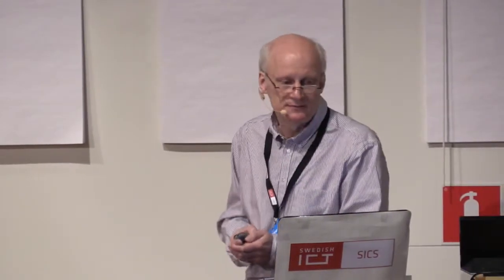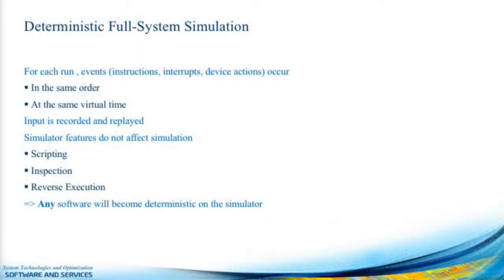So, what do we do about this? Well, what I'm proposing is to use a deterministic full system simulator. Now, that basically means that for each run, all the events that happen in the simulator, instructions, interrupts, device actions, they occur in the same order, at the same virtual time. Any input to this can be recorded and replayed, and the simulator features in themselves do not affect the simulation if you inspect something.